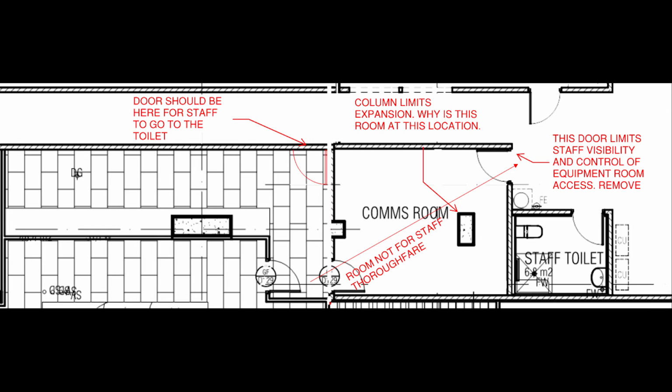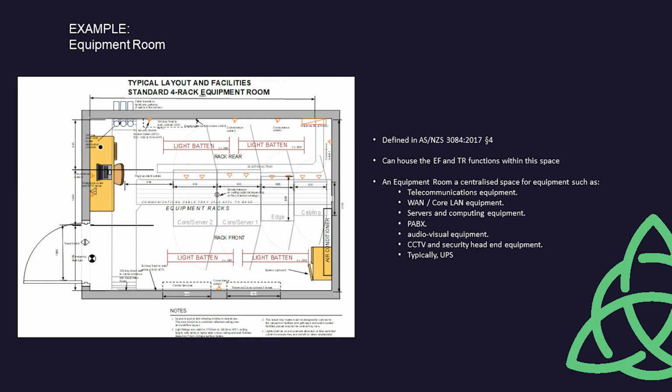The outdoor unit noise levels must comply with local authority requirements. Furthermore, they should be protected by a vandal-resistant steel mesh cage fixed to the wall or mounting pad, using anti-tamper fasteners. Any separate power outlet or switch for the outdoor unit must be of a weatherproof type, with key or padlock facility, preferably located within the protective cage. Remember to provide condensation drains.